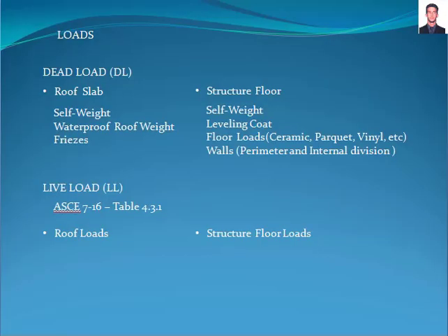Loads. After having defined the slab thickness, we can determine the loads that will be transmitted from the slab to the beams, shear walls, and columns. There are three basic types of loads: dead loads, live loads, and environmental loads. In the pre-design, we just work with the dead loads and live loads for columns and gravity load beams, and seismic loads for anti-seismic beams and shear walls.